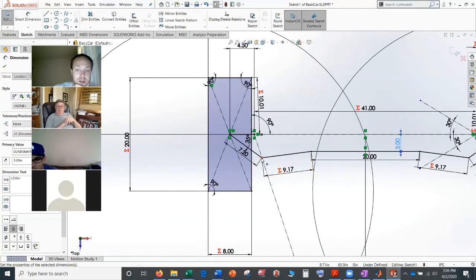Because you're hooking up on your steering arms behind your steering axis. A front steer car would come up to the front. So Baja does a front steer. Yeah, you could do the same thing, but you could hook in the front. With front steer, you can usually get better turn angles because you can see we're already kind of in line with our steering arm, basically.